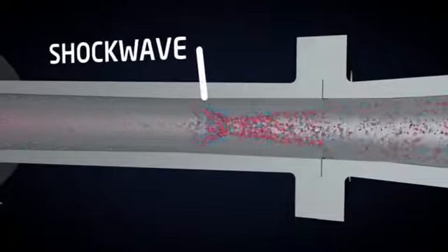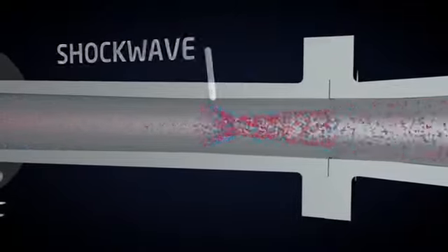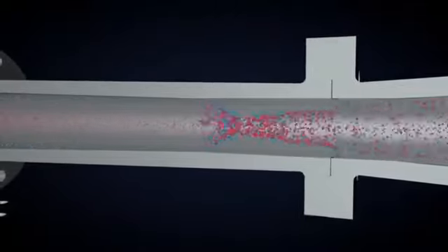The diffuser throat is sized to achieve an optimal transonic shock system. The transition from supersonic to subsonic flow across the shock system produces a dramatic increase in pressure. Slightly more than half of the total compression achieved in an ejector is obtained in this section. The static pressure, temperature, and density increase across the shock system, whereas velocity decreases.